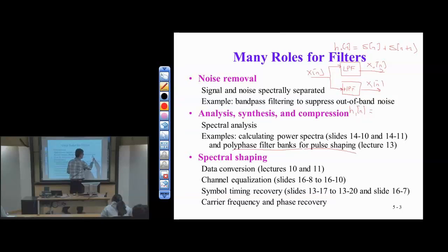Yeah, delta n minus delta n minus 1. Okay. Now we could certainly scale by a half to make it normalized in both cases. I'm giving you the unnormalized version. So that's the analysis side, to break it up into low-frequency and high-frequency components.